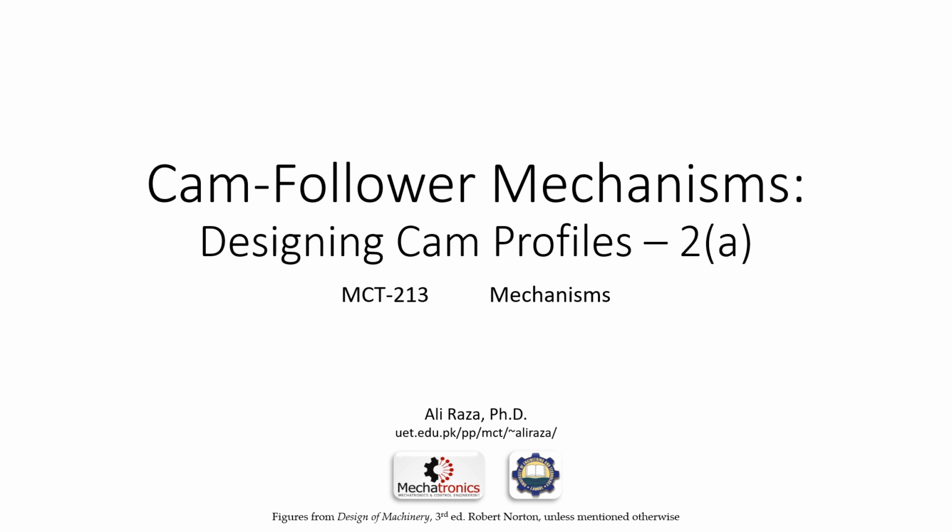So today we're going to resume the discussion on cam follower mechanisms. And within that, we were designing cam profiles. The basic idea was that we need to have a cam profile made in a sense that the SVAJ diagram indicates that the kinematics corresponding to displacement as well as velocity as well as acceleration, and in often cases jerk, is properly taken care of. And that was kind of asking us to improve the initial cam profiles. And this is exactly what we're going to resume. We're going to conclude the discussion today. So let's start the discussion.